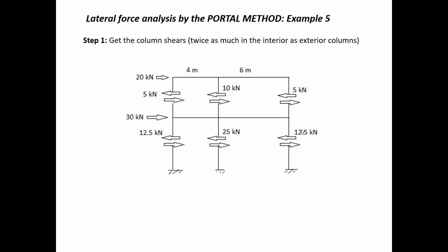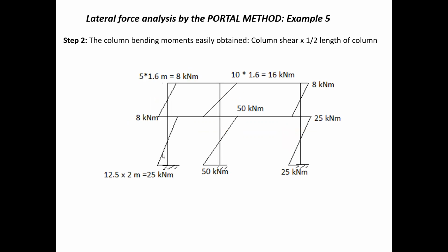And from that, you can easily get the shear force diagram. It's just this force times half the member length, right? So very, very simple. You just have to do it for one side, and the other side has to be the same because the line goes through the 0 point in the middle of the column or the beam. Okay, so there you have it there. So we left off at this point last week.